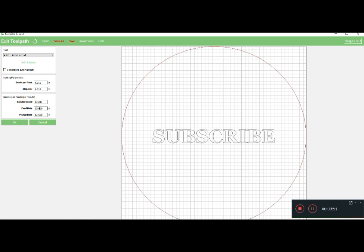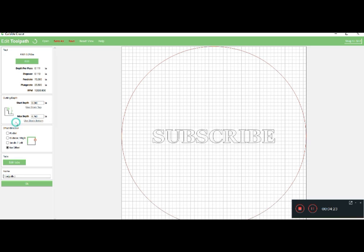But what's nice is, and I'll show you on the next episode, on the G code, the Carbide Motion, you can actually manually adjust your speeds as long as you have them set up high enough in here. So we'll keep that at 75. Plunge rate, it's fine. I think the plunge rate is okay. We can even bring that up to 25. It's not a big deal. That is how fast your plunge is going to go down and up. But again, you can set that manually once we actually start using the Carbide Motion. So I think this is fine. We're going to hit OK.